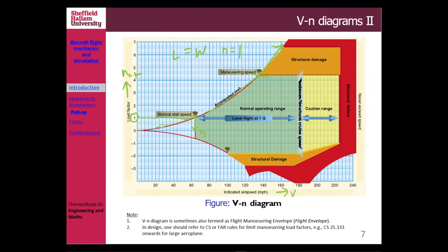At some point, it will then disintegrate. I think that g force, or n equals 6.5 perhaps, in these examples. But of course, as I said, there is a limit more important than the structural one, which is the human being who flies the aircraft. Obviously, the human being can only sustain, I think, below 4.4 in this case, and sometimes just about 2.5 or between 2.5 to 3 point something, which is actually defined in your CS25.